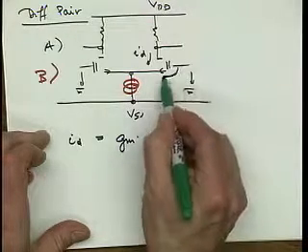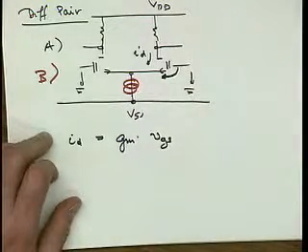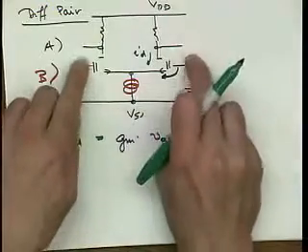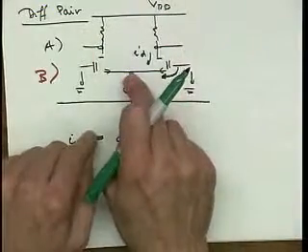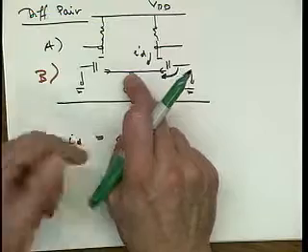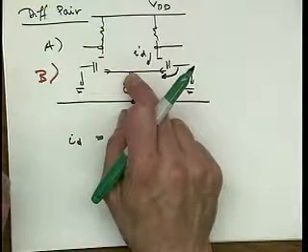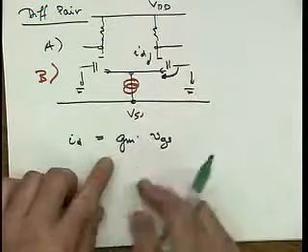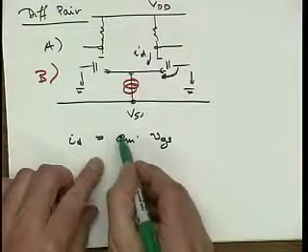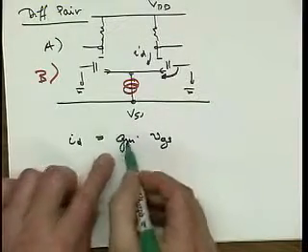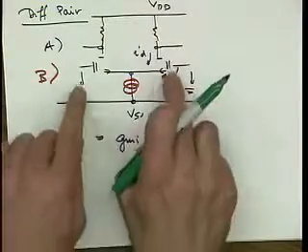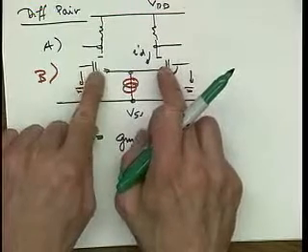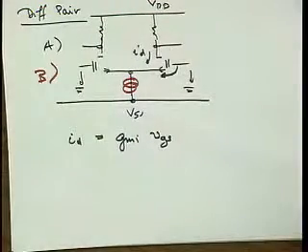That's this voltage here. And if I increase the common voltage here, then the voltage here in the center tap is also going to increase. Consequently, even if I get a mismatch between the two transistors, GM1 and GM2 not quite identical, the net difference of current flowing here is not going to be that large.